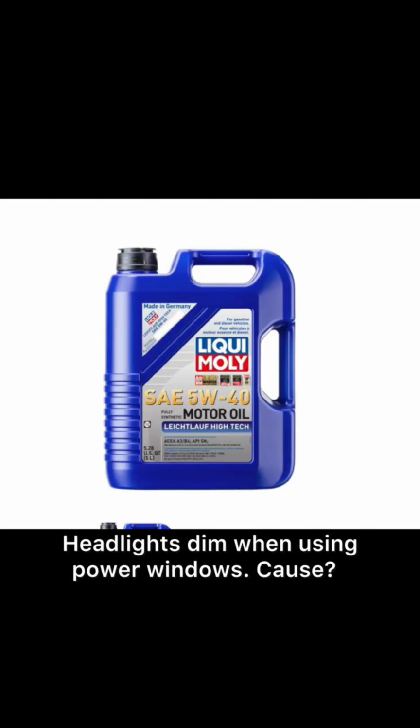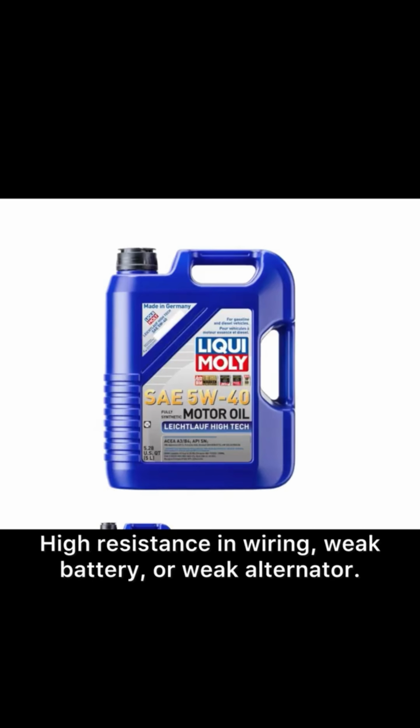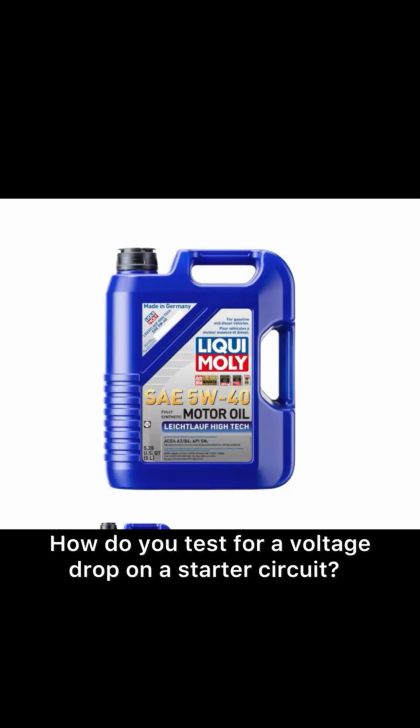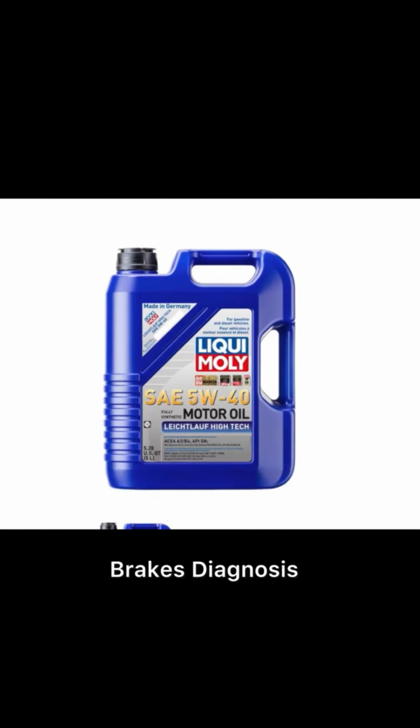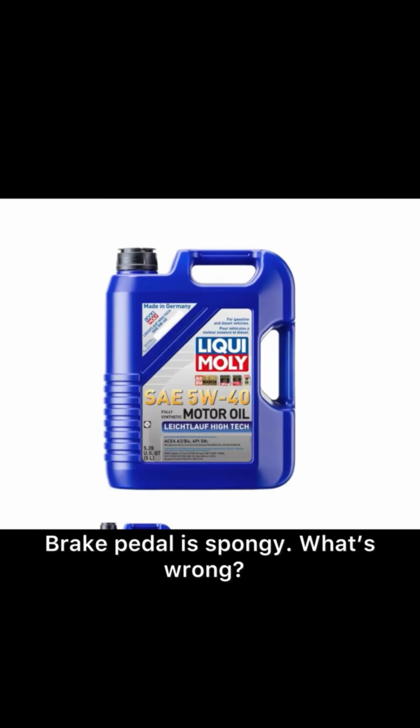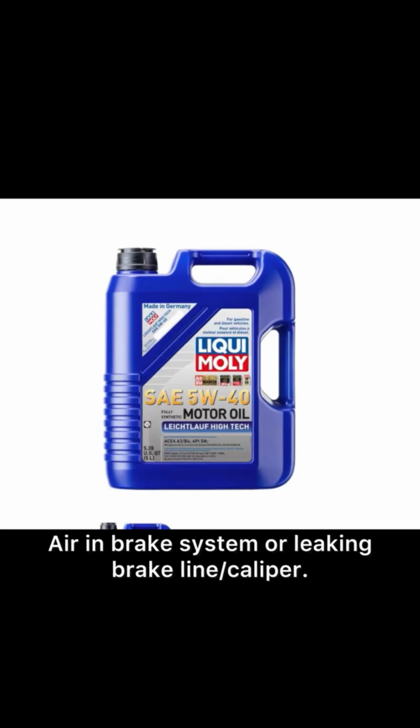Headlights dim when using power windows. Cause: high resistance in wiring, weak battery, or weak alternator. How do you test for a voltage drop on a starter circuit? Use multimeter across battery positive and starter terminal during cranking. More than 0.5 V drop indicates high resistance. Brakes diagnosis: brake pedal is spongy. What's wrong? Air in brake system or leaking brake line/caliper.